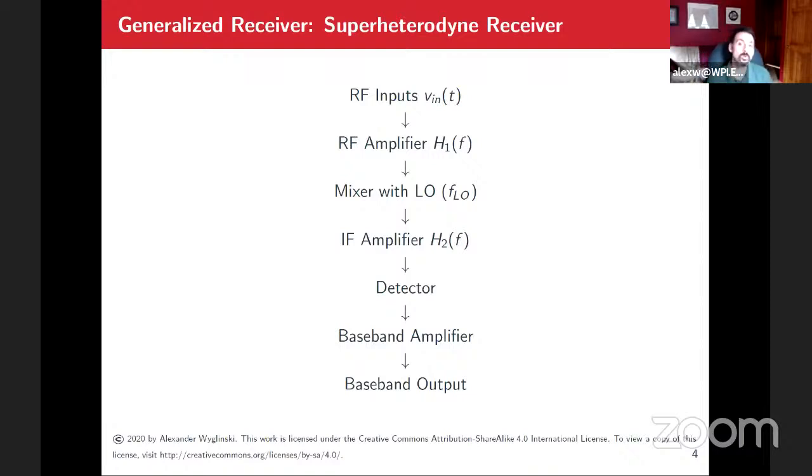Now, this is also a source of problems because when you wonder about the frequency offset, in many ways, that's coming from things like your local oscillator, because local oscillators are not perfect. Again, that's a topic for the follow-on course here with respect to 4305. So what you got to do is you need to have good local oscillators. Now, the problem is the higher the frequency of the local oscillator, they're more expensive.